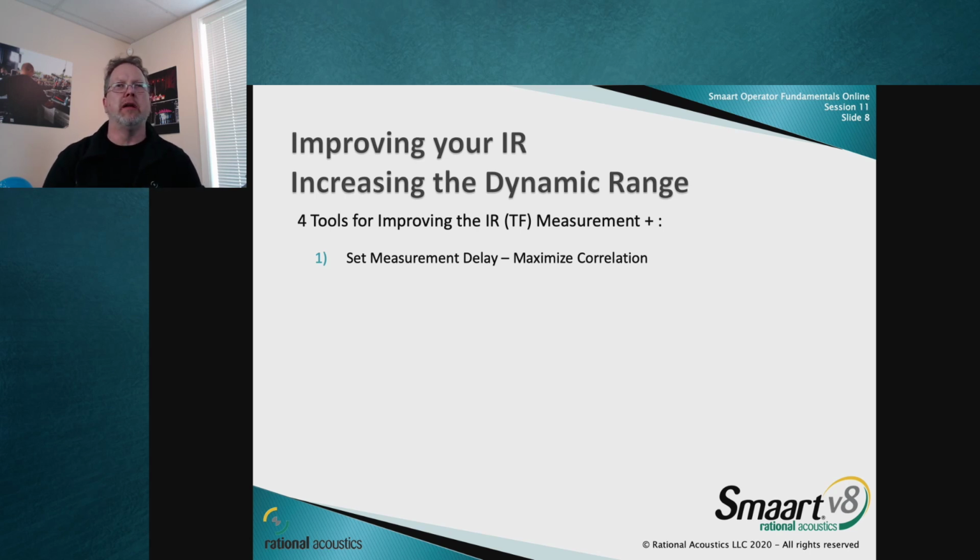Functionally, the way I look at it is, we've taken a chunk of the wave that we've sent into the system, and then we're looking to see how long it takes for that chunk of wave to show up at my microphone position, and whether multiples of that wave show up as reflections and reverberance. So timing our reference to our measurement signal gives us the best correlation there. That's going to help with our measurement.